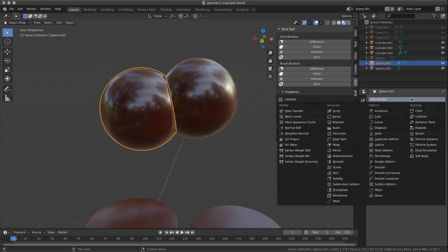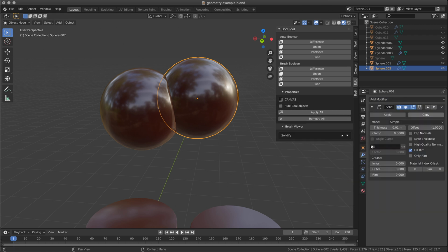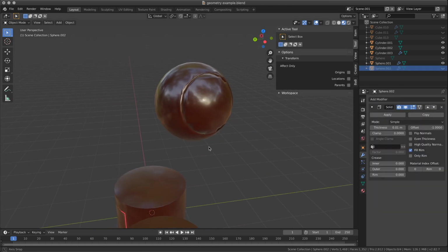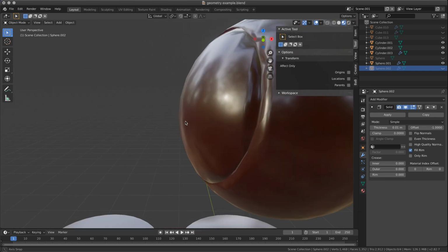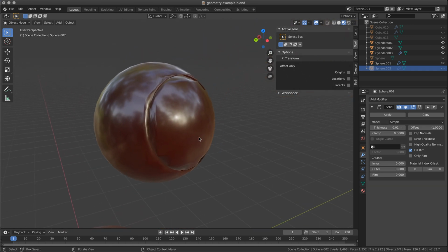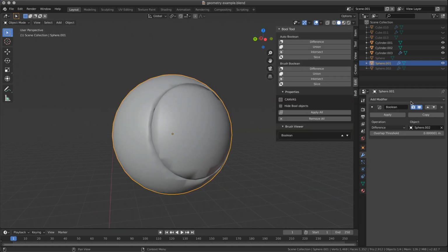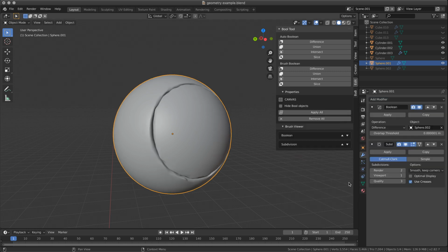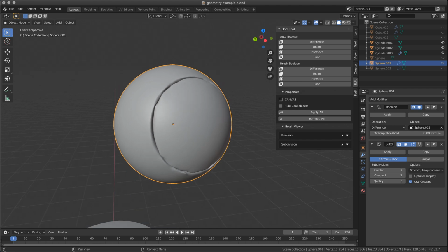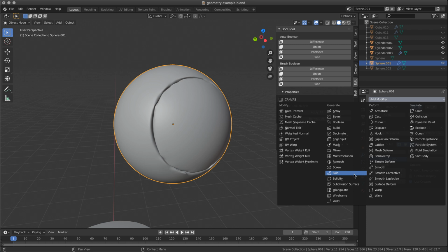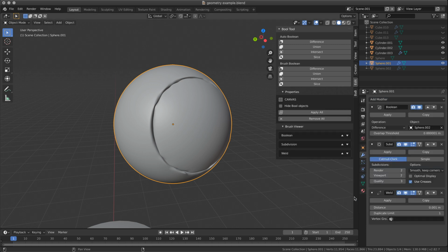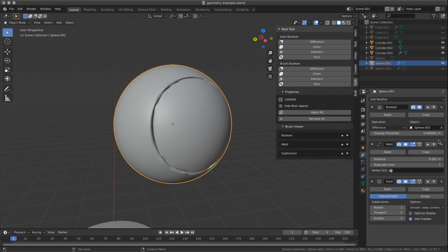and then on the second one we apply a solidify. We'll hide the second one, and still we have a messy result. Is it a bit better? Probably. Still very low poly, but we can at this point add the subdivision. It's still a bit good, but it's not ideal. Let's try with the weld that I will add before the subdivision.